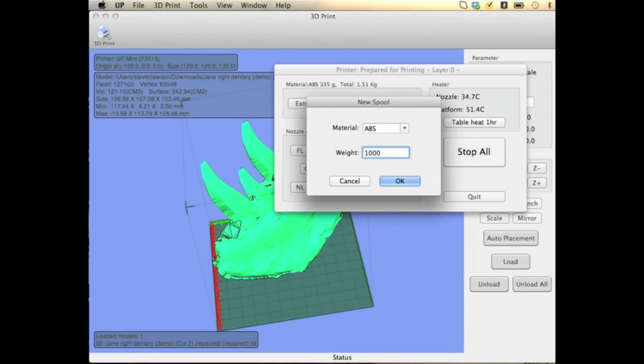You have an option of materials to use, and for replicas of vertebrate fossils, ABS plastic has to be your option. ABS is more flexible than PLA, but has a much higher melting temperature, 270 degrees Celsius, compared to PLA, which can sag over time. And if we want to make scientifically viable casts of fossil specimens, we don't want sagging, because sagging is going to create a false morphology.